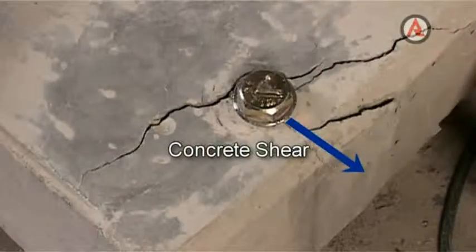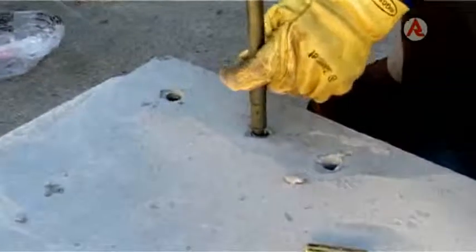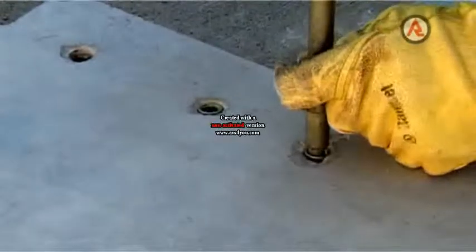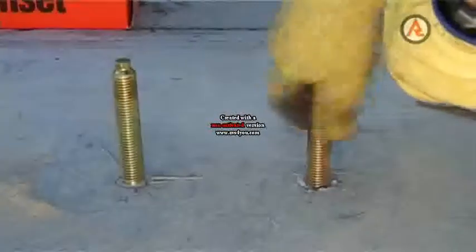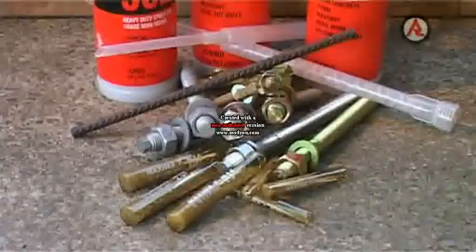With expansion-type mechanical masonry anchors, edge distance is especially important to load capacity, as the expansion of the anchor itself places a load on the surrounding masonry, tending to break away the edge. This problem is accentuated with multiple expansion anchors placed in line along an edge. In close-edge situations, it may be necessary to use an alternative Ramset Masonry anchor, which does not place stress on